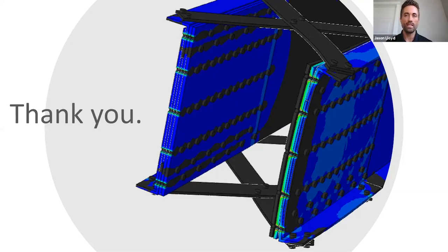And so what we found in the beginning is that these built-up members are much more efficient in terms of resisting fracture than we really give them credit for. And so what we had to do in the laboratory is force conditions that would never exist in the real world. And that's where those hydraulic wedges come into play. So we would attempt to fracture, and if it didn't fracture on its own, then we would apply these hydraulic wedges into the notches. If you can imagine, what that does is open up that notch and force a really intense crack tip opening, which drives up the stress intensity factor at that crack tip and forces a propagation of the fracture.